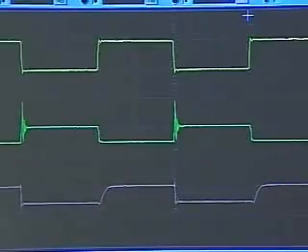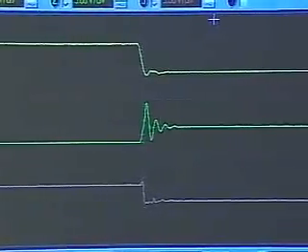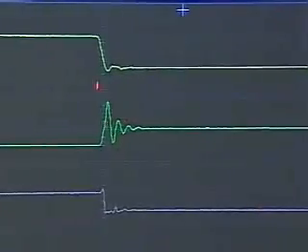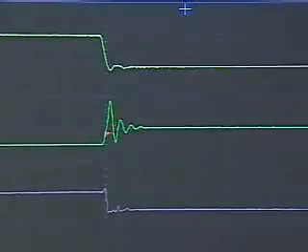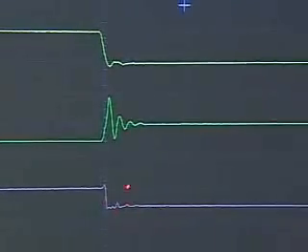And that's a real problem, by the way. And the reason that's a real problem is the following. Okay, look at this. Look down here. Because this intermediate voltage is meandering all over the countryside here, at this particular point the intermediate voltage dips quite low. And because it dips quite low, look at the output. The output has a bump here. And it's quite possible for this output bump to now go into the forbidden region.